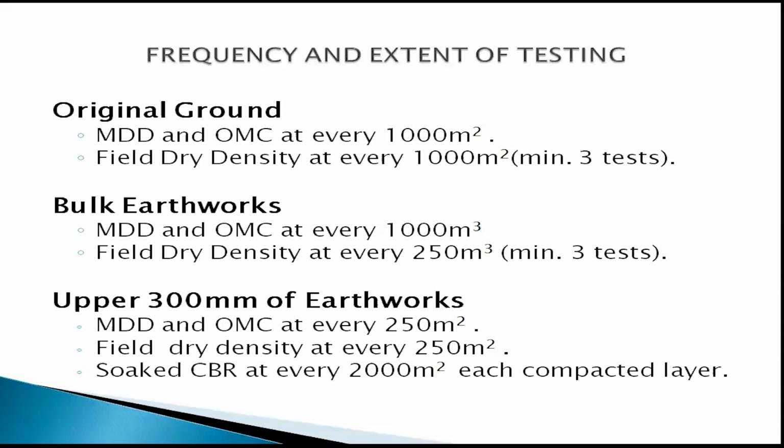So for 250 meters squared of the compacted layer, we need to determine the field dry density. We need to do the field density test to determine the level of compaction and also determine the moisture content.